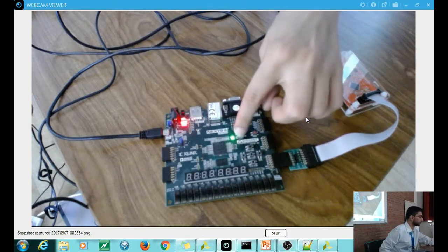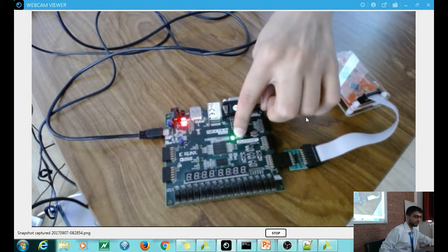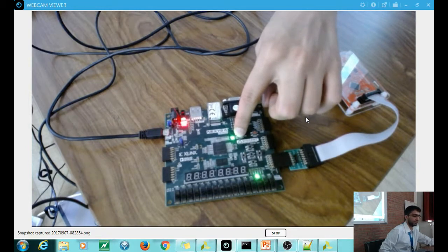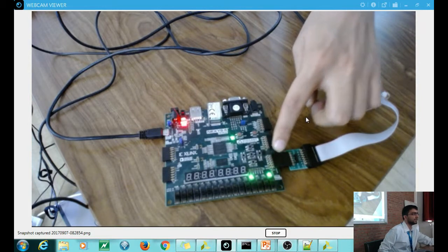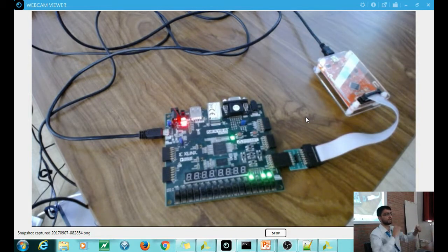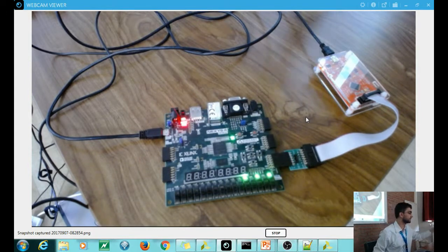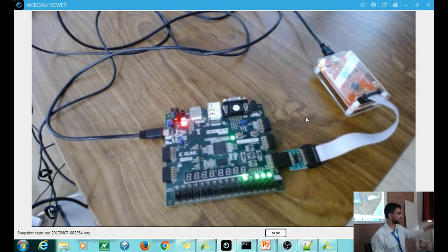So after programming, you have to press the reset button once to reset the core, and then you should start seeing LEDs increment here. This is just a program which is in the program memory itself, in the bit stream itself. Remember I mentioned a while ago that you can splice code into the bit stream itself. So within the RTL we just wrote a short loop which basically loops through LEDs.